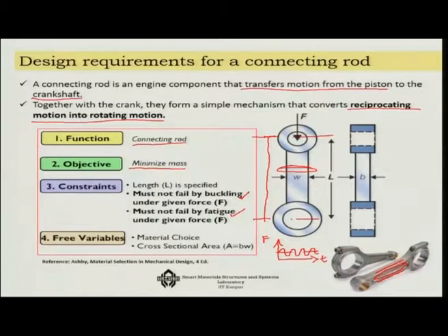I will not talk about it today, but the resonating frequency is also of concern. If you reduce the mass, the natural frequency of the system, which is square root of k by m, goes up as you reduce the mass. So, this would not resonate. That is one of the strategies that they take.